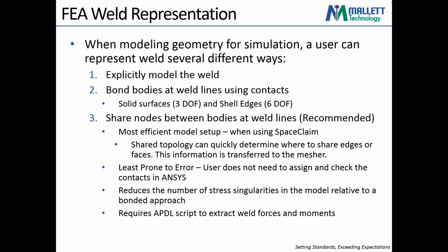Another benefit of this is it reduces the number of stress singularities in the model relative to the bonded approach, number 2. And the one drawback, there may be others, but the one drawback that I really see in this approach is that it does require an APDL script to extract weld forces and moments. Essentially, you can no longer query the junctions. You actually have to extract those forces via script.